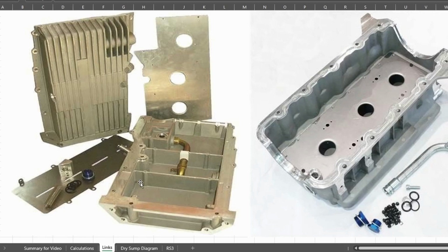So you're not going to get the immediate slosh away and that immediate drain away from the pickup. You're going to get the oil moving to a different area in the contained area, but it's not going to transition between the different compartments that easily. And then your pickup is in the middle, it would seem, and so that's where it scavenges oil.